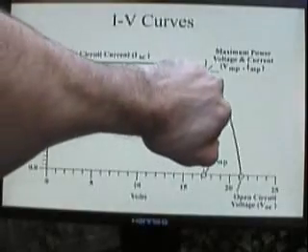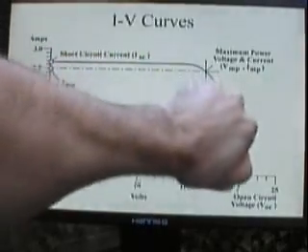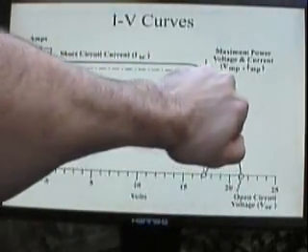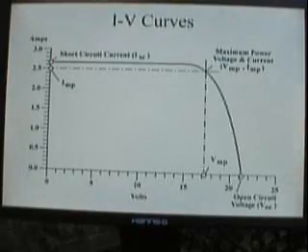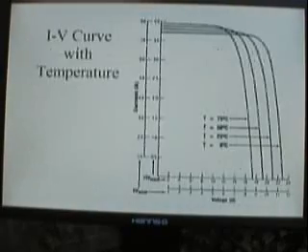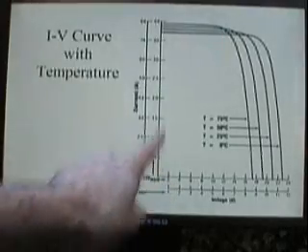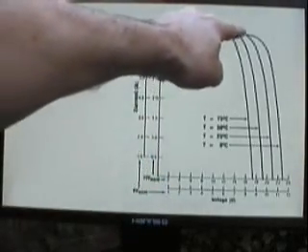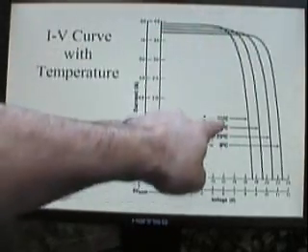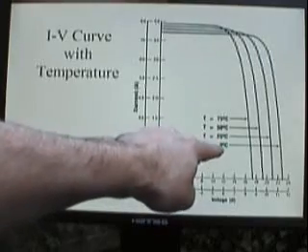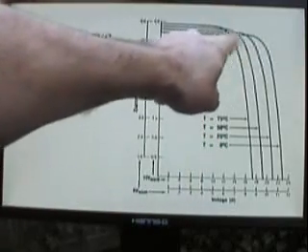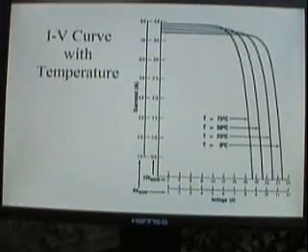And this is the max power point, where ideally the system operates right about that point on the knee of the curve. That changes with different temperatures, and this would be for crystal silicon. The knee is in a different place depending on different operating temperatures, so you have to adjust accordingly with balance of systems equipment. The end.